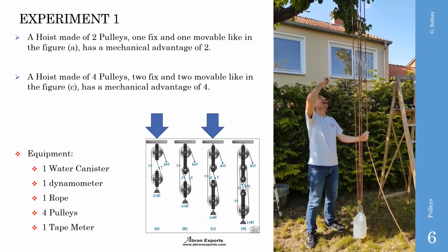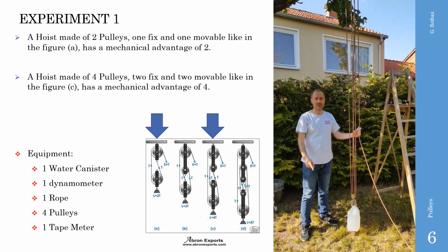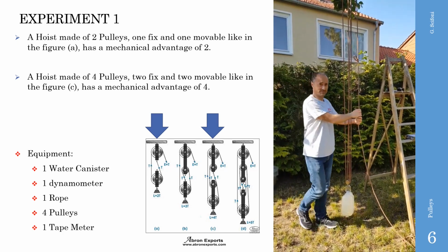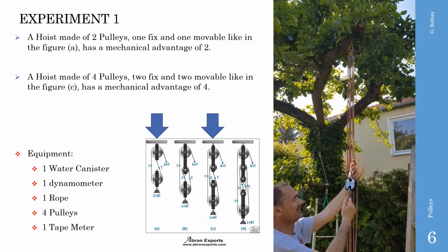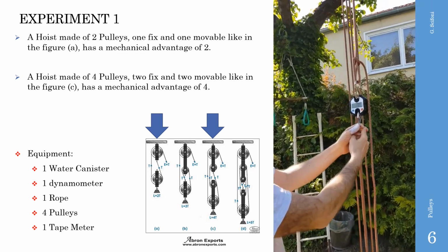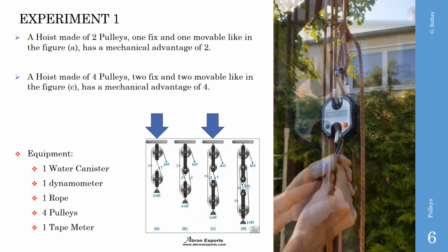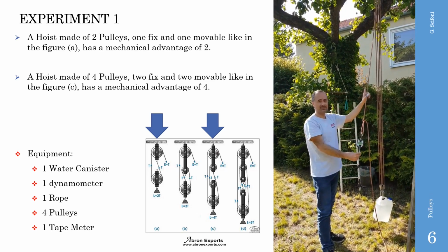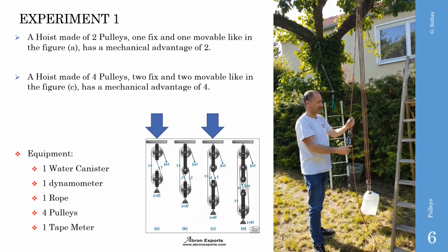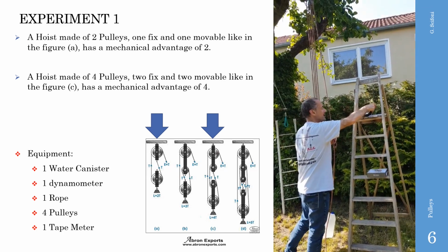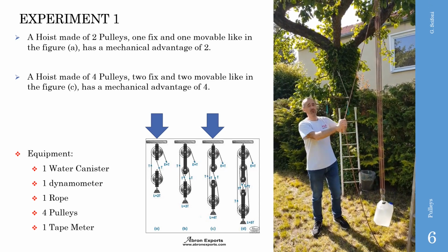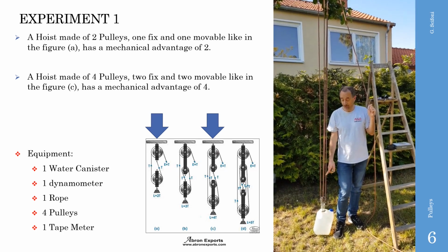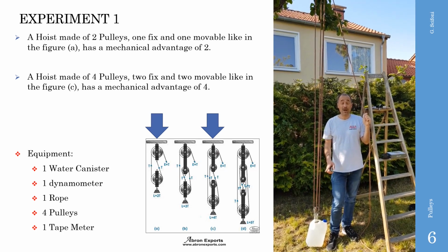Now we have added another pulley up, another pulley down, totally 4 pulleys. And we meter the force for lifting it. Should be 125. Actually, 1/4 of the load is a lift needed for that. Eventually, the force is divided by the number of pulleys. Totally we have 4.